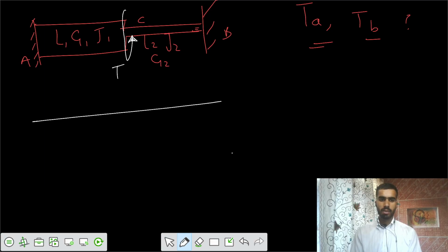I would say this is your line diagram. TA rotates with your right hand anti-clockwise, which means the thumb points toward the support B. That's your T. That means here would be some resistance of TA in the opposite direction. Similarly, here would be some TB. So we get TB equals T minus TA.